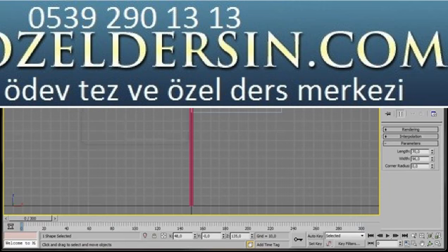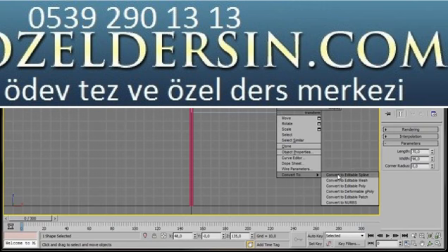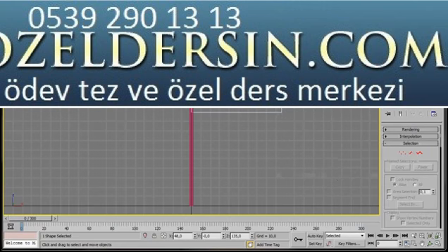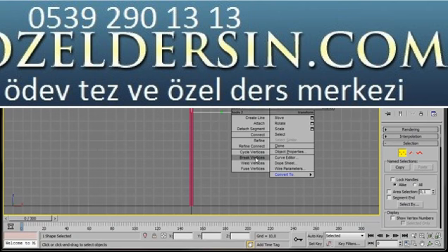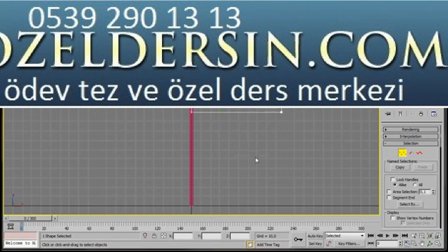Now we're going to right click on the rectangle, and from the flyout menu, we're going to select Editable Spline. Now we'll go up to the Editable Spline subdivision level, and we're going to click on Vertex. We're going to select all the vertices, right click, and then from the flyout menu, click on Break Vertices. If we don't break all the vertices when we add our Garment Maker modifier, we'll end up with odd-shaped or rounded corners. So we'll go over now to the Modify list.